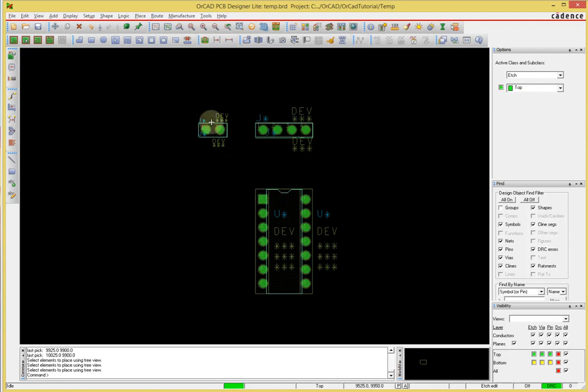So you can look at these footprints on a sheet of paper, and if you already have the parts, let's say you purchased them already, you can just place the parts on your sheet of paper and see if the pins line up. You will be able to tell right away whether you are way off or whether you need to rethink your strategy.